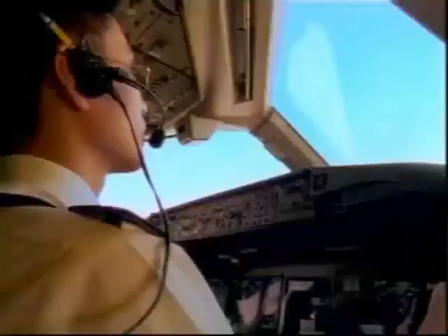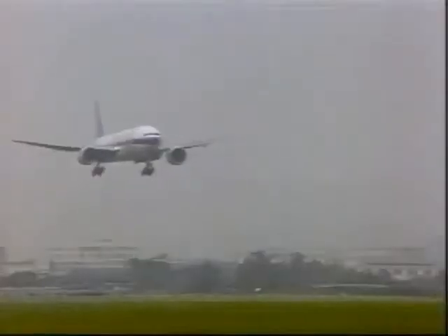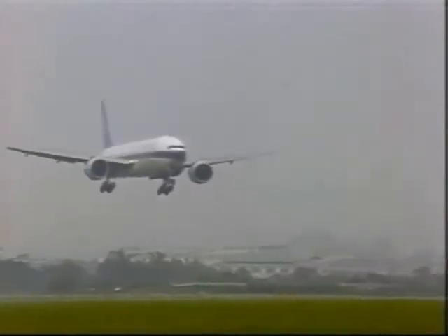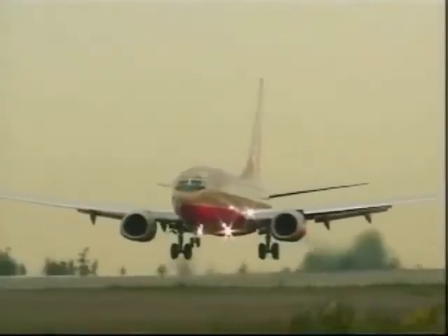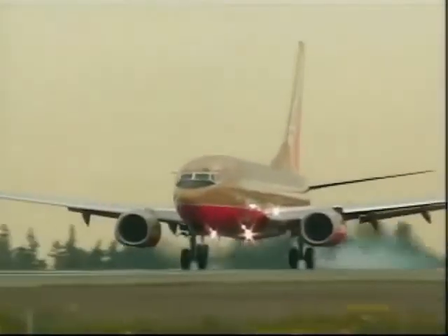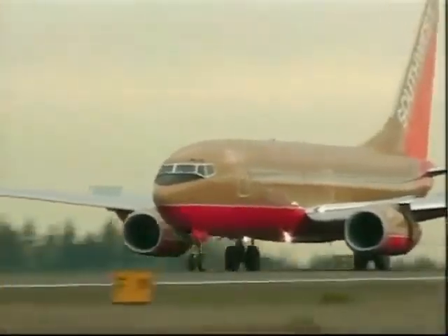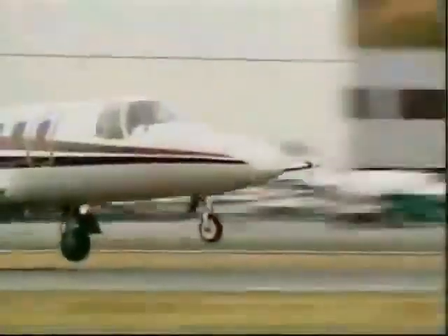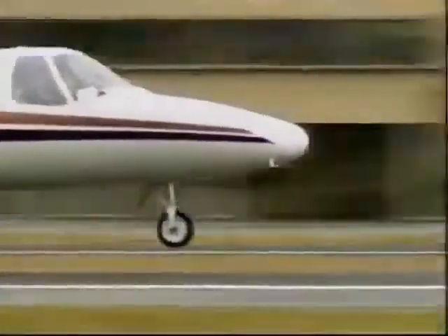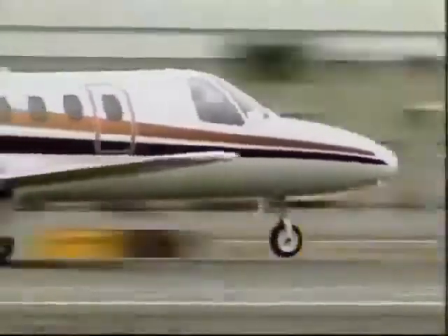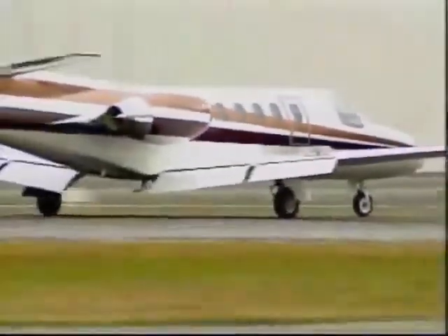A key factor in making the go-around decision is to constantly reassess your decision to land during the approach. Note that there is a time when it is no longer appropriate to go around. For example, when spoilers and thrust reversers have been deployed. Your operational procedures should have appropriate information regarding these situations, and you should follow those procedures.